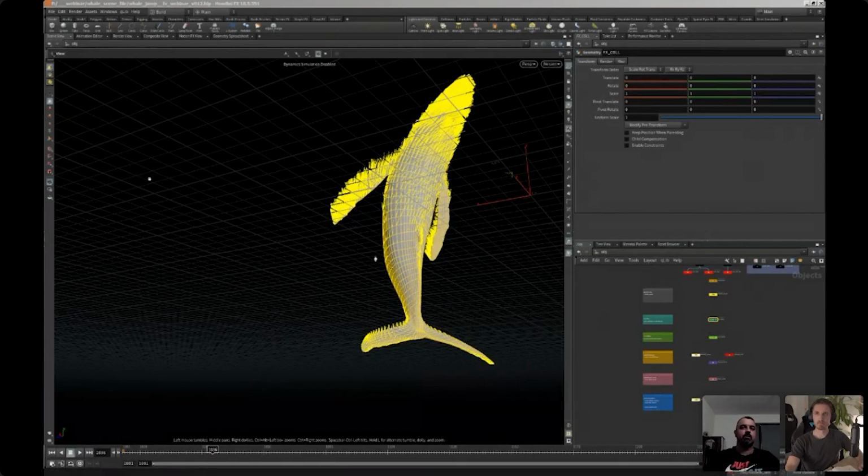It's just a waste of resources. But that's why you use wedges. If you have the impact of an object, for example, you can see where your limit is. Maybe on the first wedge it's going out of the container. Using pop drag to slow down the droplets, maybe you need a few meters. Okay, I extend the container a bit more, maybe with a few more tweaks it's not going out of our scene. But it really depends on what you have.